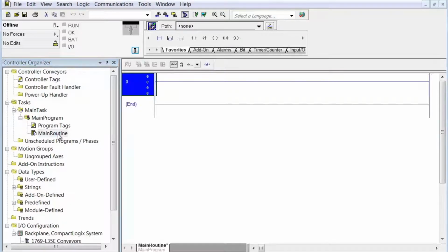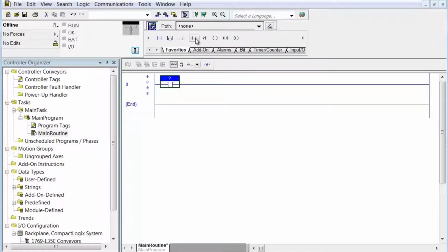So double click. It gives us a rung, so we're going to throw in a true if on, and an energize output. And we're going to call this System Run Enable. You see I abbreviated a little, and I use upper and lower cases to give me a type of delimiter in the text to make it more readable. So Sys Run Enable, that's pretty clear, System Run Enable.